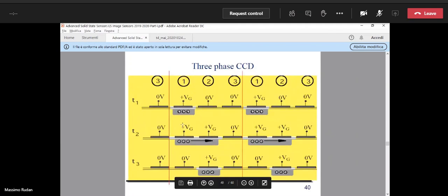If you consider a CCD, there is only one reading device that is, for instance, placed at the right-hand side of the CCD. All charge packets are moved along the same channel and eventually end up in the same position at the end of the CCD. So there is only one reading device.